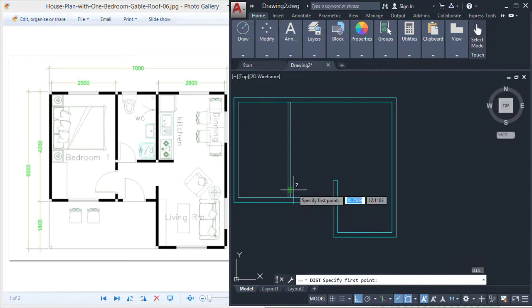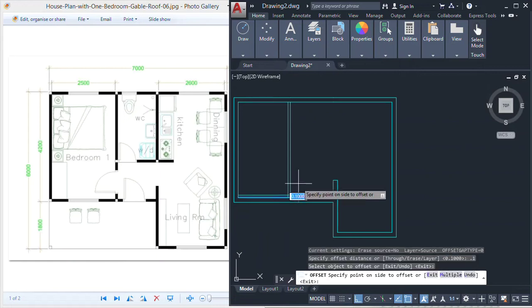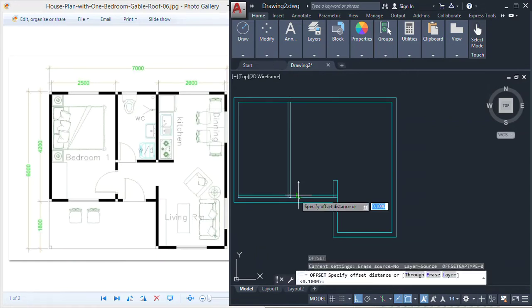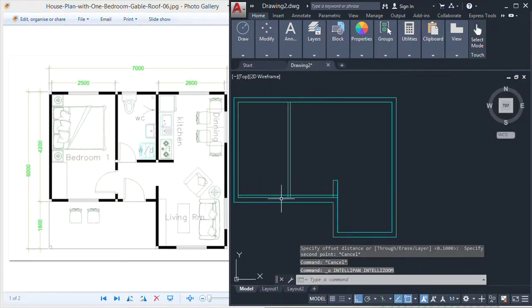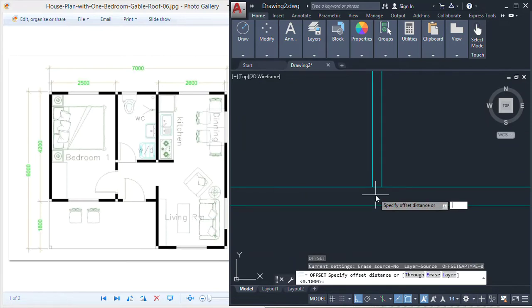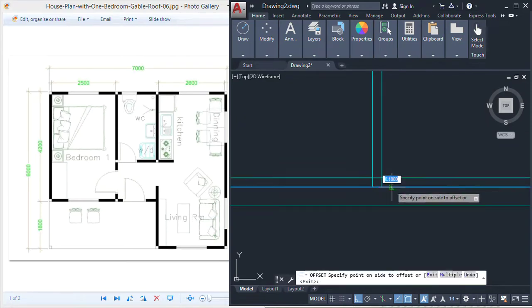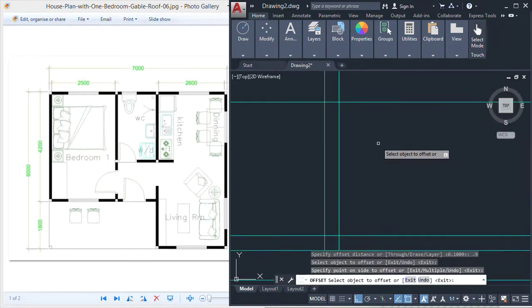And then I know that my doors are about 90 centimeters and I need an extra 10 centimeters for the opening part. So I'm gonna ortho, let me do this again so you would see. I came here, I orthoed a 10 centimeters line, and then again ortho, and I gave it 90 centimeters this time, and then again I ortho this line.